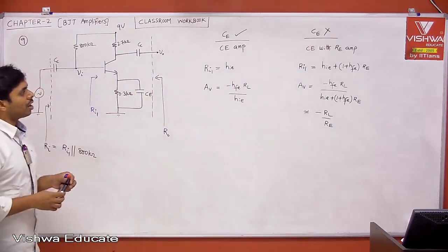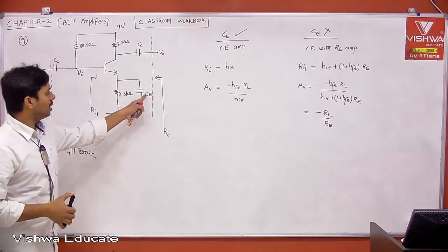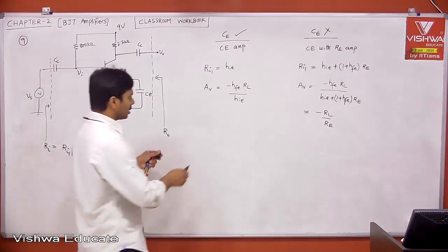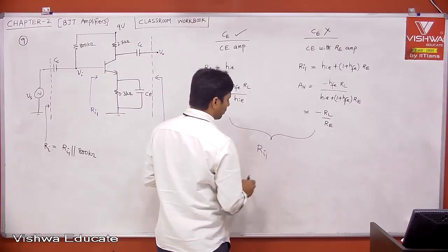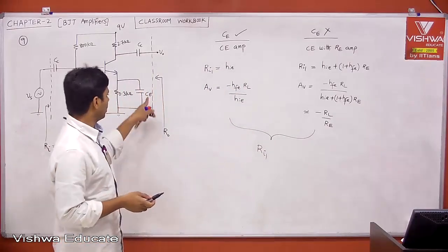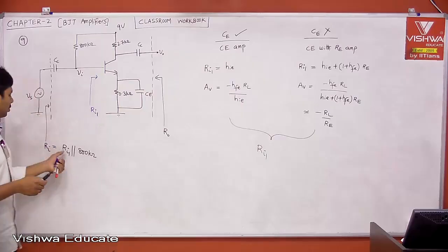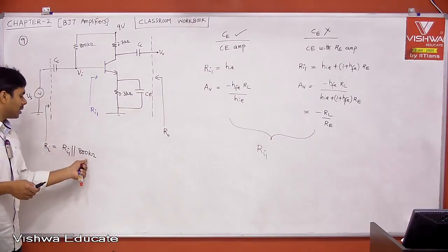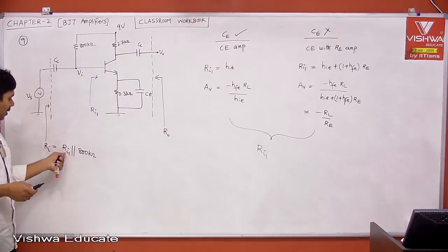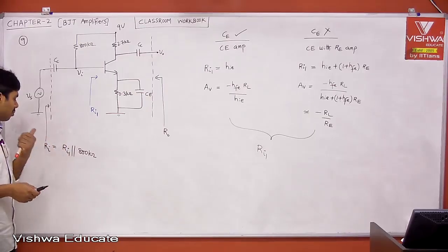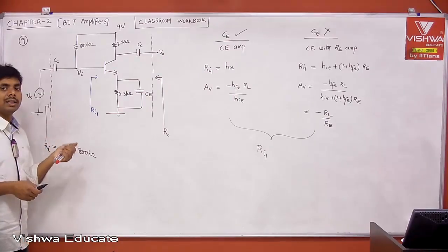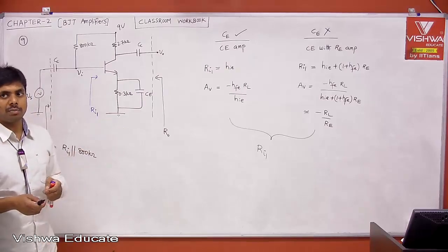Therefore, now we got to know. Tell me, if CE is disconnected, overall observation, what about your input impedance from your transistor, Ri1? I am not speaking about Ri, because Ri1 in parallel to 800K is nothing but your Ri. If you know Ri1, then we can comment on Ri, because we are not calculating absolute input impedance, we are calculating increases or decreases. That is your problem statement.